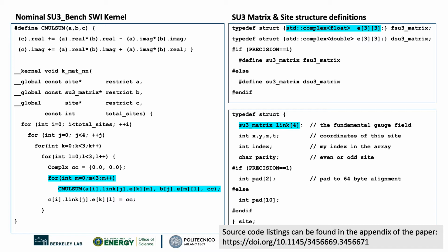The size of the lattice is nominally 32 to the fourth for a total of over 1 million sites and a memory footprint of over 640 megabytes. For the Xilinx analysis, the size of the lattice was reduced to 16 to the fourth in order to fit into a single bank of high bandwidth memory. However, the size of the lattice for benchmarking only needs to be sufficiently larger than any local cache, and since the Xilinx device doesn't contain a cache, this was not an issue.